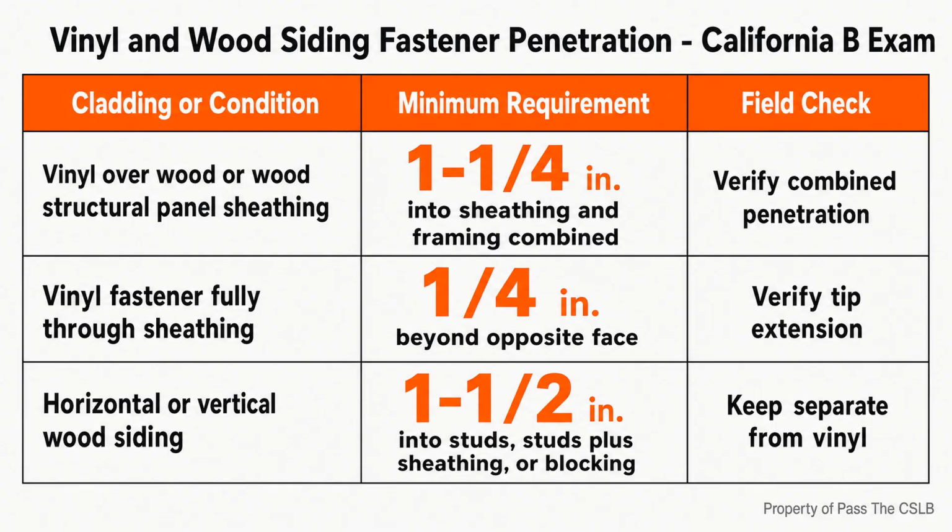Trim is where drainage, attachment, and movement often meet in one small area. Projecting wood trim requires continuous flashing above it. Window and door openings need flashing integrated with the water-resistive barrier. Wall and roof intersections also need approved corrosion-resistant flashing. Each of those locations interrupts the broad wall surface, so the field condition has to reconnect the drainage path around the interruption.